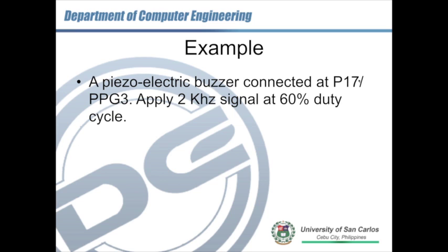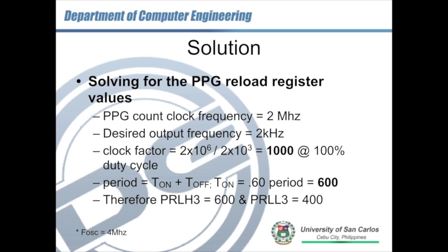It's connected at P17, with the alternate function of P17 being the PPG output, one of the PPG output pins. So before we start, we have to solve for the value of the PPG reload register.